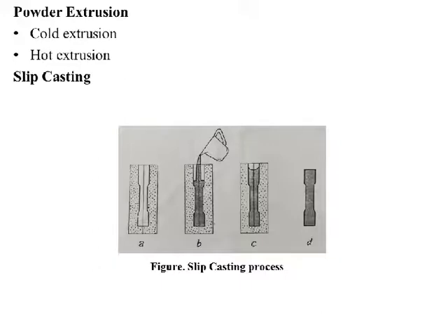Next, we require proper preparation of a slip. Slip is nothing but the mixture of the slurry that we pour into this POP mold. This slip consists of various powders, deflocculant, and water. All these are mixed in proper ratio, and then it is poured into the plaster of Paris mold and allowed to set for 10 to 20 hours.